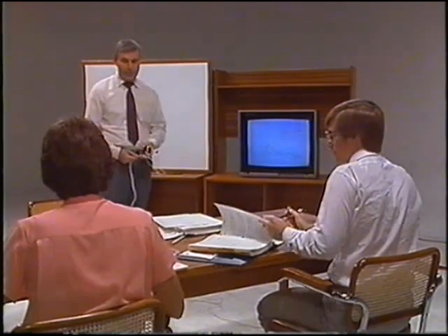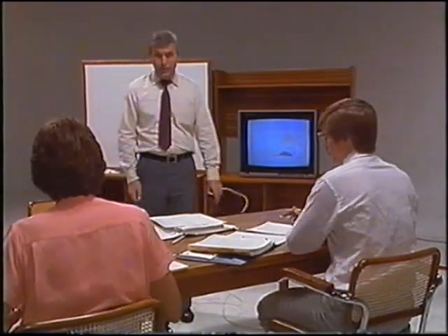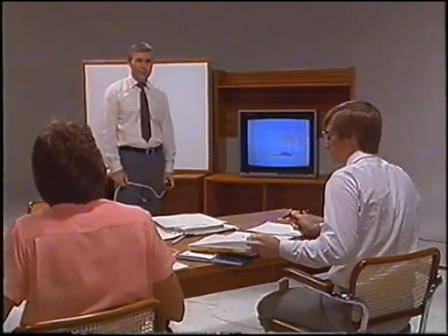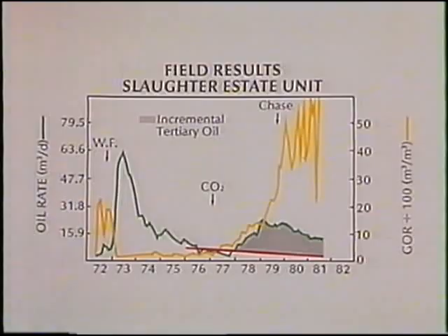I'd like to talk now about two field case histories. Both of these are in their own right sort of clever projects. And I've selected these because they are basically worlds apart in solvent flooding application. The first one is the field results for the CO2 flood in the Slaughter Estate unit. Actually, this was a sour CO2 flood, with 20-some-odd percent of H2S dissolved in the CO2, which, as we've already seen, will enhance the miscibility of CO2. And this is a flood being done in a West Texas carbonate reservoir of the order of 5,000 feet deep, modest viscosity crude, and very tight, 10 millidarcies or thereabouts.